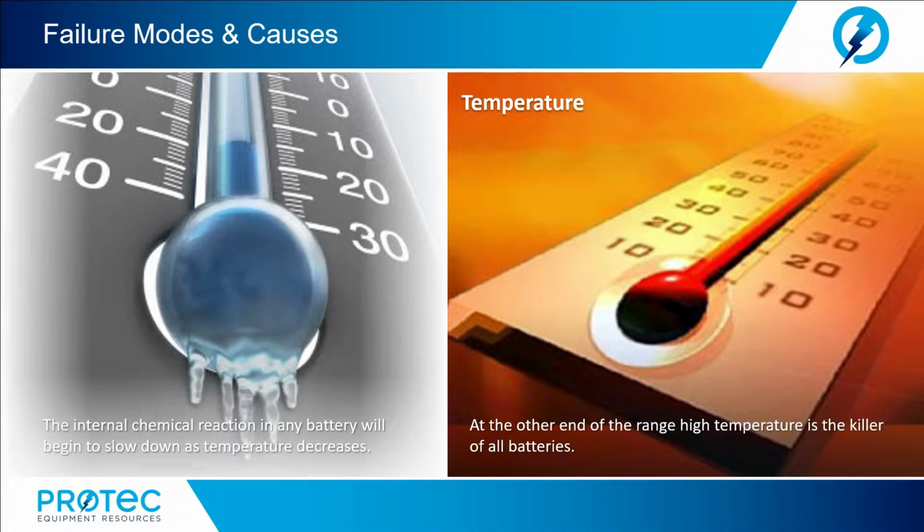The increased temperature causes faster positive grid corrosion as well as other failure modes. By holding a lead-acid battery at 95 degrees Fahrenheit instead of its designed 77 degrees Fahrenheit, a 20-year battery will last only 10 years, a 10-year battery only 5 years, and so on. Increase the temperature yet another 18 degrees Fahrenheit up to 113 degrees Fahrenheit, and a 20-year battery will last only 5 years.